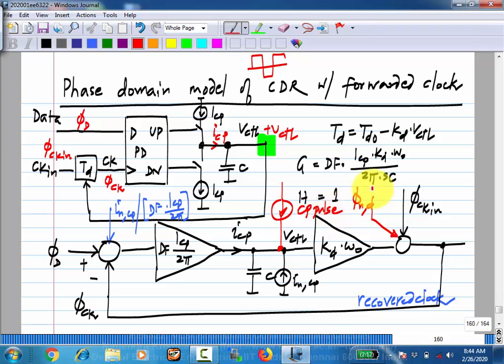So this is in general true of every phase detector. The average output of the phase detector follows the phase difference, but in addition to that, there will be some periodic error, some jumping of signal back and forth. So now this also causes similarly periodic error in the output phase. This is not so important with the linear phase detector, but with other kinds of phase detectors it will become important, as we will see in the bang-bang phase detector and so on.